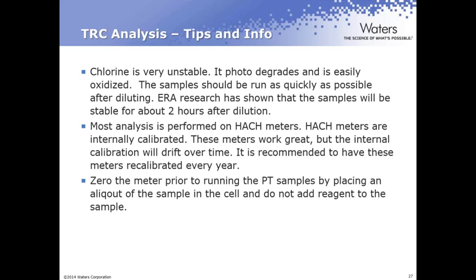aliquot out. So let's talk about a few tips and some information regarding chlorine analysis. One thing please remember is that chlorine is very unstable. For those of you that work in treatment facilities, chlorine is what's called a 15-minute test. And it's called a 15-minute test because chlorine not only photodegrades, but it's easily oxidized.